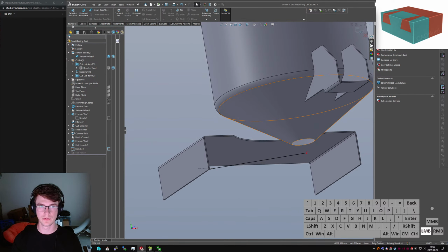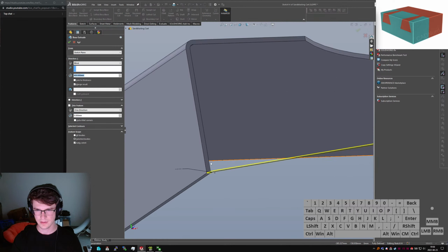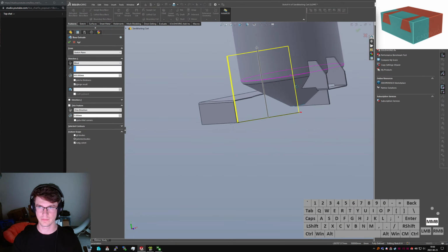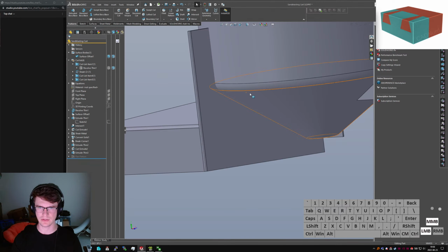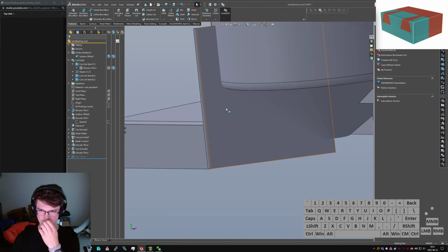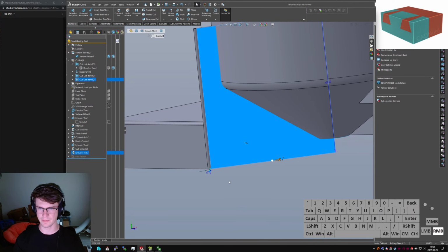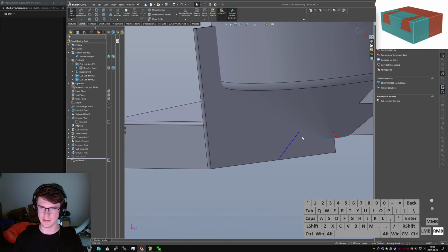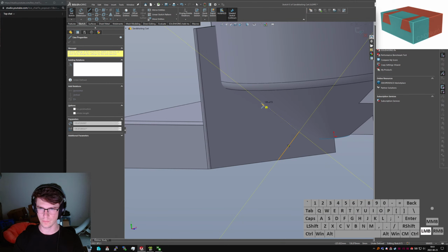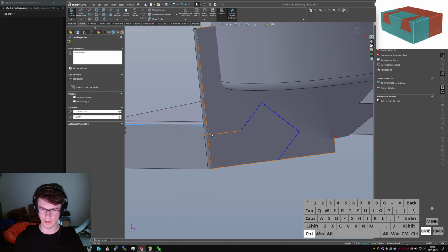And then we'll do extruded, nope, not extruded cut, sorry. Extruded boss. Extruded up. 450's probably fine. Yeah, and we'll skip merging too, actually, so that I can be a little more strategic in how I place my cuts. And then I'll do an extruded cut on this plane, specifically because that lets me be a little more careful about where I'm making flat points.